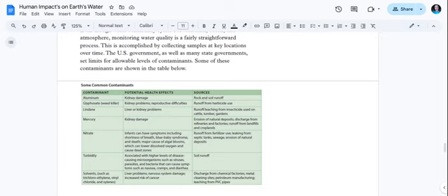Turbidity, this is a new word. Potential health effects of turbidity: it is associated with higher levels of disease-causing microorganisms such as viruses, parasites, and bacteria that can cause symptoms such as nausea, cramps, and diarrhea. That comes from soil runoff. Turbidity is how clear the water is. Water with high turbidity is not clear at all. Water with low turbidity is almost completely clear. Very, very low turbidity means that the water is clear.